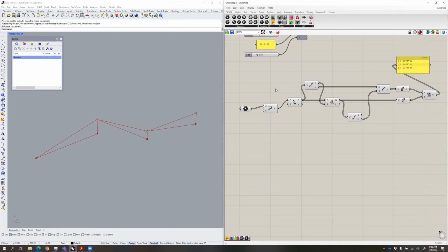So now all we need to do is find some way to visualize this on that line that we've drawn. What we're going to do now is extract a point along this line, where the label for the slope can sit. There's a component called point on curve. And the reason it's called point on curve is because you can create a point on curve. That was my smart Alec comment. So we're going to use this tool and get a point on each segment.